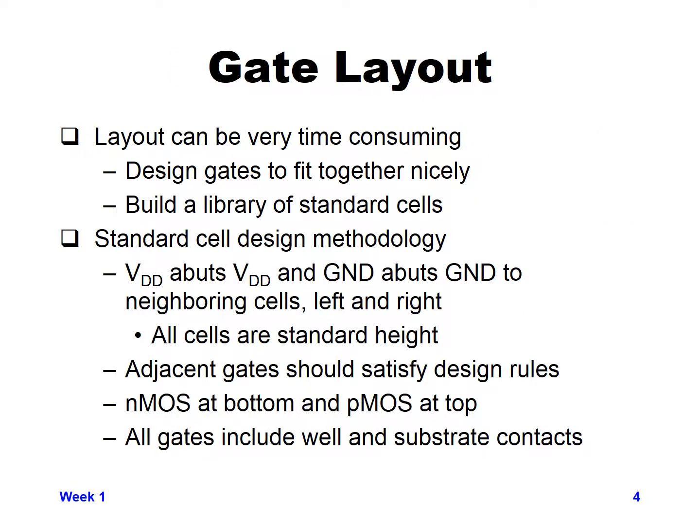So hopefully this short introduction into layout and integrated circuit fabrication has given you a little bit of respect for how difficult and time-consuming layout can be. Basically, just to create an inverter, you can see there are many different layers that you need to draw in, and you have to satisfy various design rules, get all the sizes correct, etc. And so I just want to emphasize that layout can be very time consuming to do.